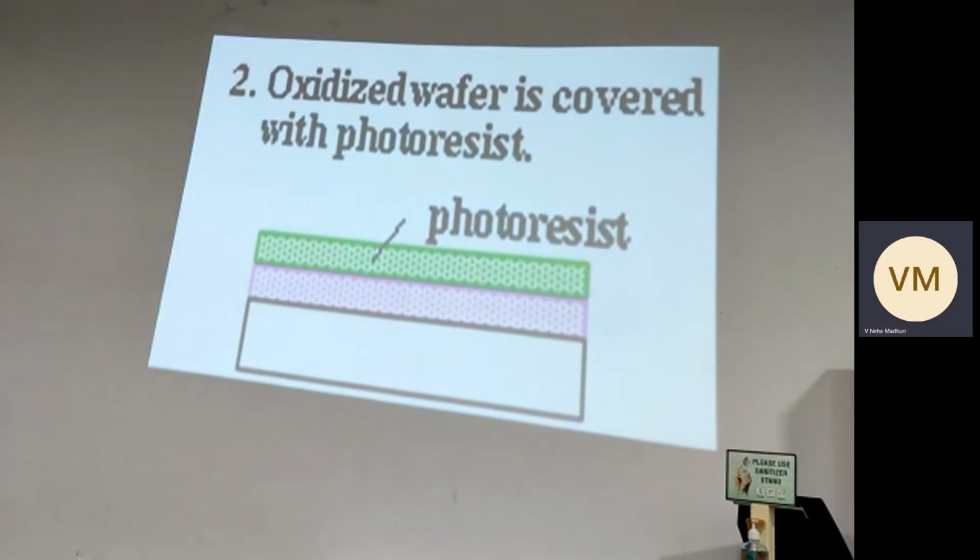So this guy is explaining his own process. Like he wants to oxidize first the whole complete layer, and then. That is a good procedure, because we are now on the silicon. We first cover everything with an oxidized layer so that our wafer is saved. Whatever we want, we can selectively etch and then use those areas.